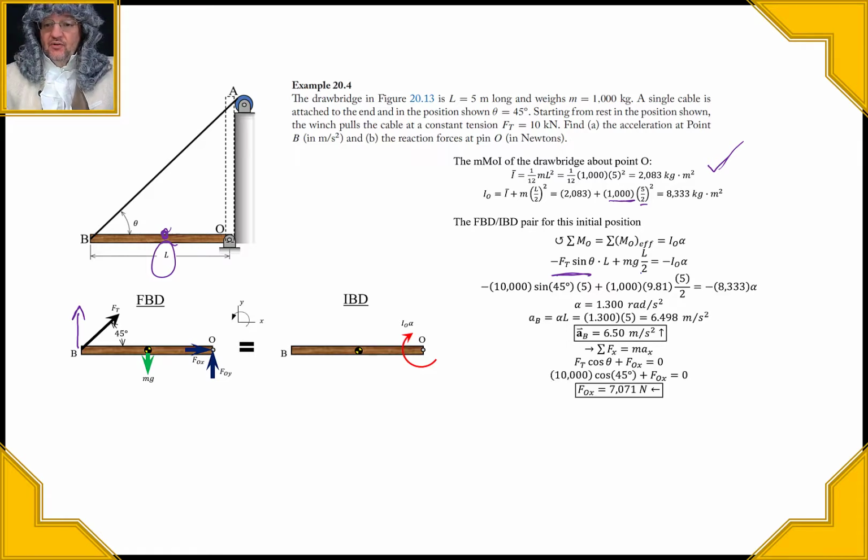But we have to be careful in the y direction right here. We didn't draw this thing on here, and perhaps we should have. We should have drawn mass times the acceleration in the tangential direction, which we could do in the y direction right there. I didn't draw it on my free body diagram, and it probably should have been, but I think I didn't draw it because I didn't want people to double dip. But that was a mistake by not having it on there.